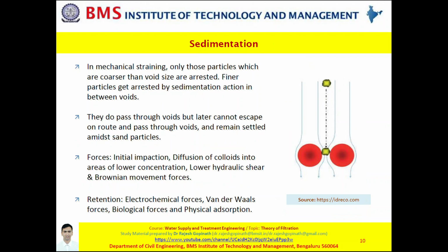Sedimentation. If you recollect, I told you that most of the removal happens in the first few centimeters. Then how is it that the depth below it is helping infiltration to take place? Now let's look at the sketch on your slide. As the particles come through the water and try to pass through the sand, they get stuck in the top layers.